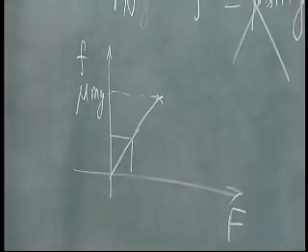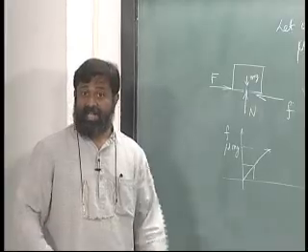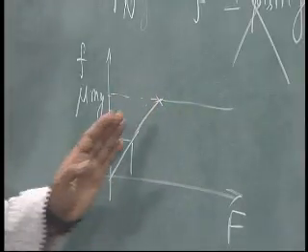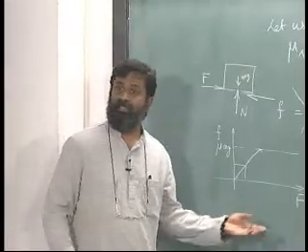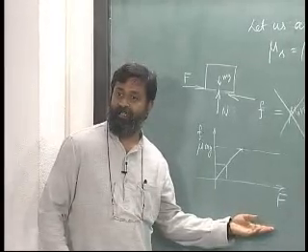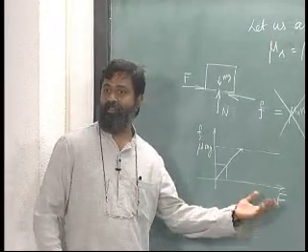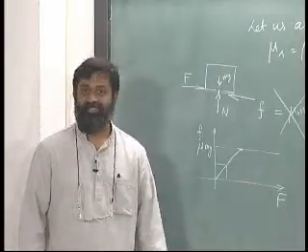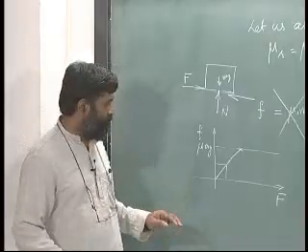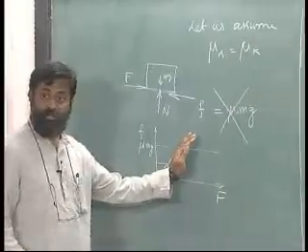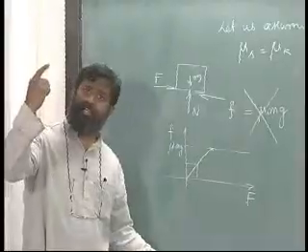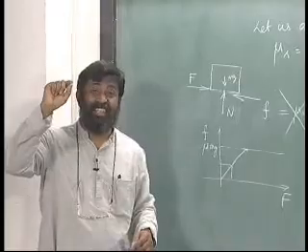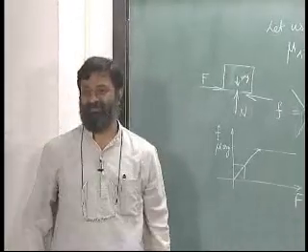Can the force F increase? It can increase, supposing it goes like this. What happened to the additional force that has been offered? The additional force offered goes towards accelerating the body. Is this understood? This is very important. So if I am looking at static situation, it is only one instant when F is equal to mu times mg, that is at the threshold of starting to move.